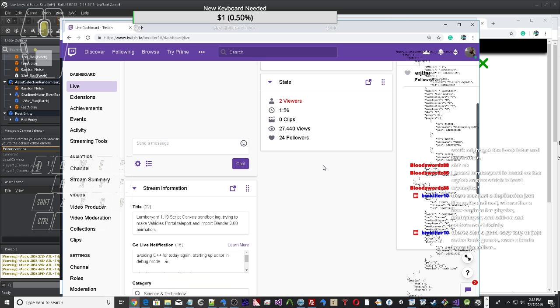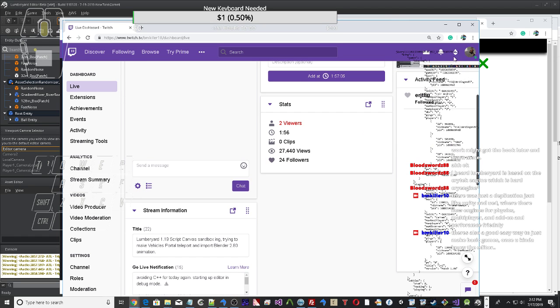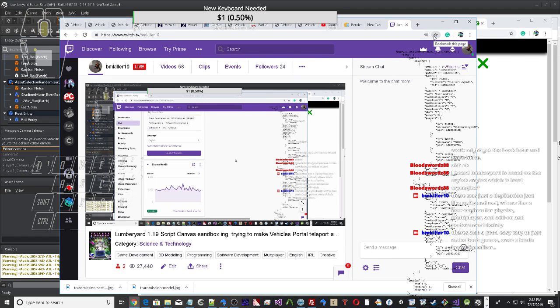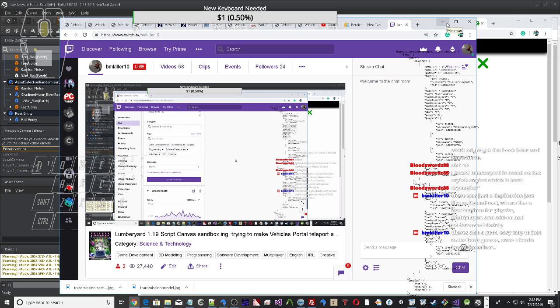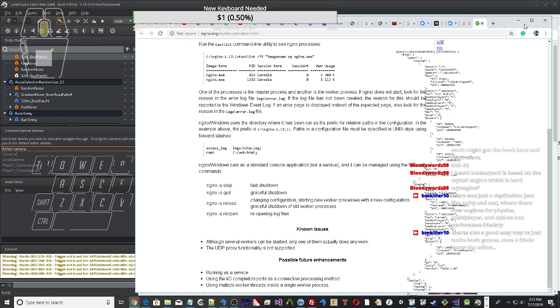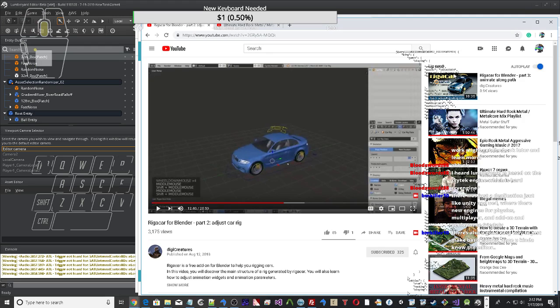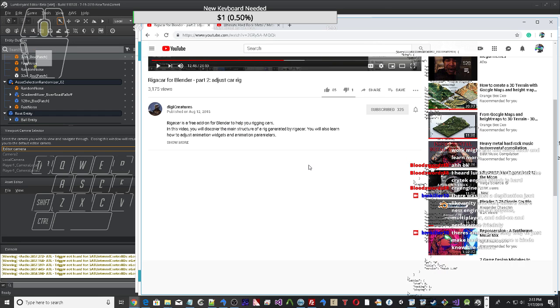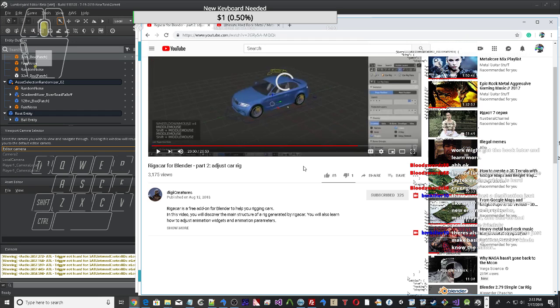The magic formula yields the longitudinal force, in newtons, given some constants and dynamic inputs. The formula takes 11 empirical numbers that characterize a particular tire: B0, B1, through B10. The dynamic parameters are Fz, or weight, in kilonewtons on the tire, and the instantaneous slip. The 11 numbers are measured for each tire.